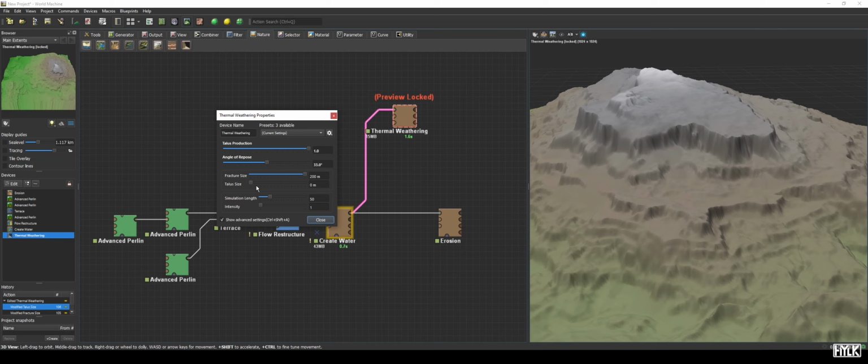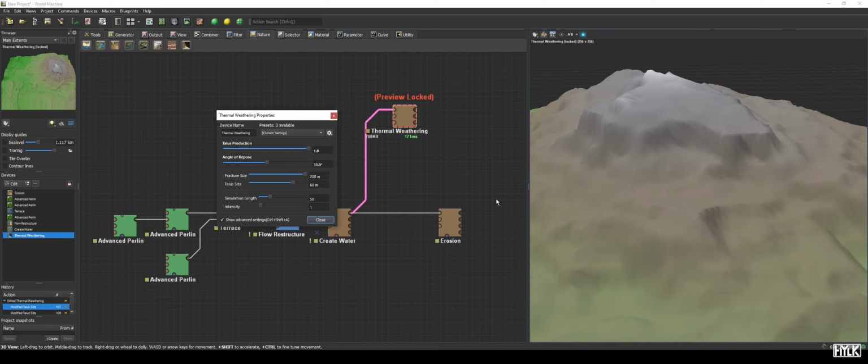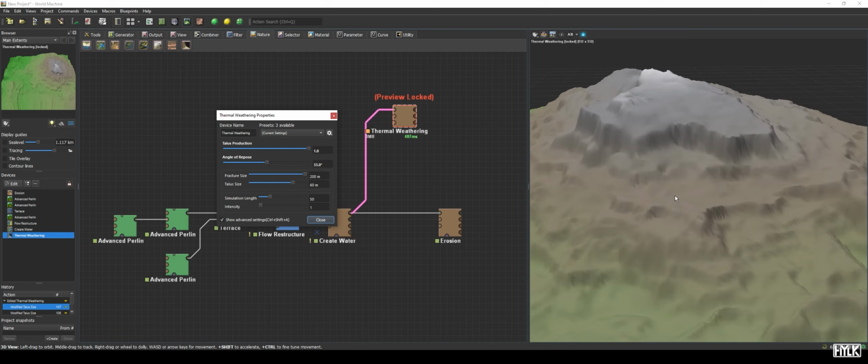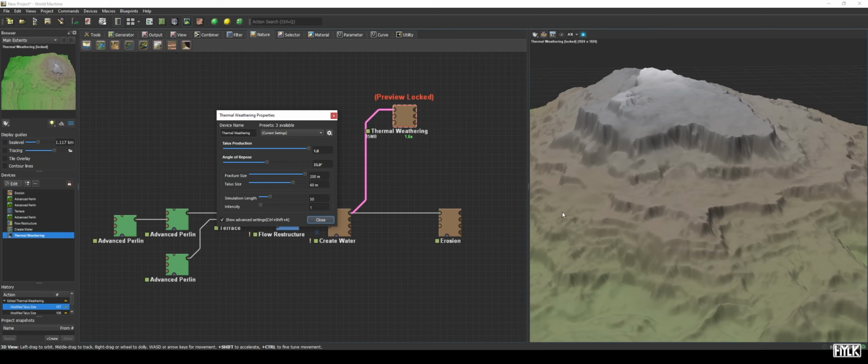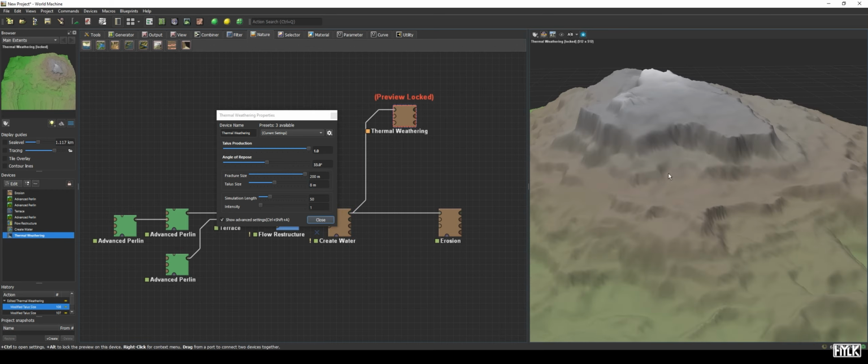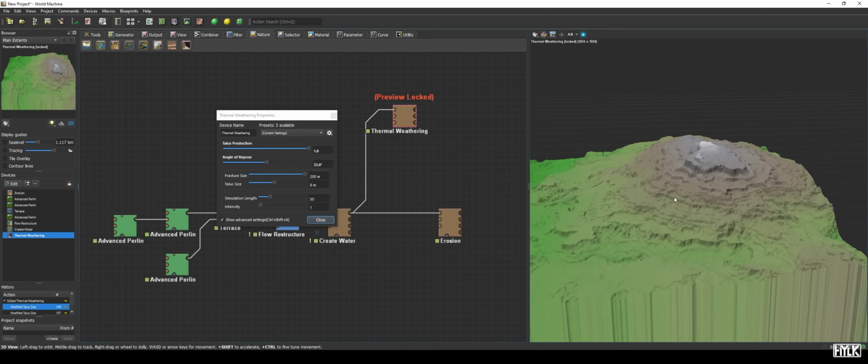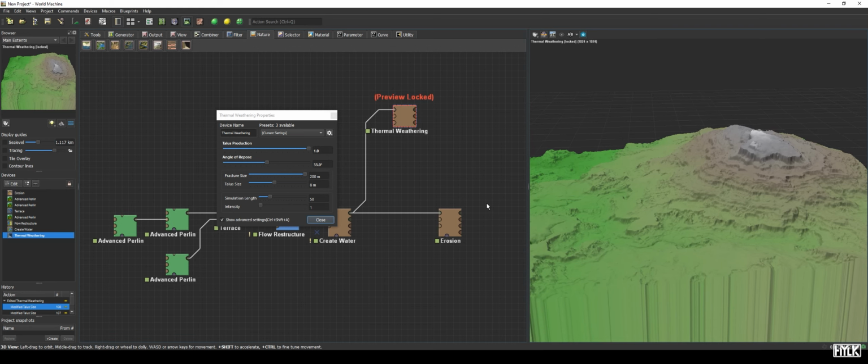For quick preview purposes, this emulation can be a handy feature, but I recommend against using it if you want to have some more control over the final talus. For example, if you were to import this into a game engine, you can add rocks by yourself on this slope to create a better, higher detailed talus, instead of relying on the, well, ultimately lower resolution mesh of the terrain. Or if you use materials, you are better off creating a rock material with a good normal map, which can have a lot more detail as well.